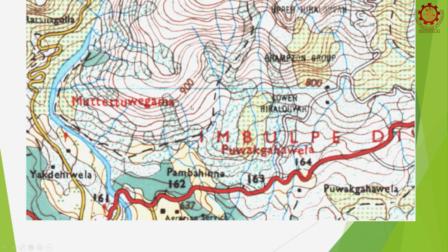In between you can see there are 4 lines or 5 sections. I will take the pen. Here you can see this is 800, this is 900. So, there is 1, 2, 3, 4 and 5 sections. Therefore, each section has a height of 20 meters. Therefore, these light lines in between have a height difference of 20 meters, right. So, 800, 820, 840, 860, 880, 900, right.